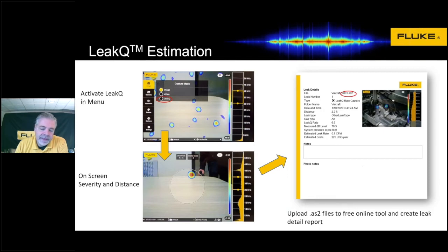We can come back and calculate the actual cost of that leak every year. This is used primarily for prioritization of your leaks. You may have 20, 30 leaks that you've captured this way. It might be nice to know which one is the biggest one because you only have time to fix 2 or 3 today. That's what can help you prioritize where your leaks are coming from.